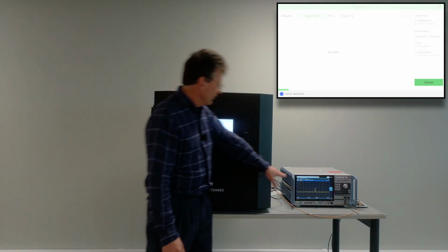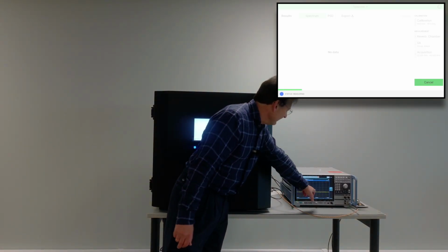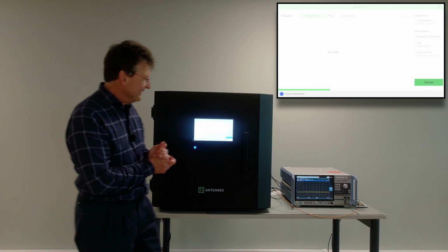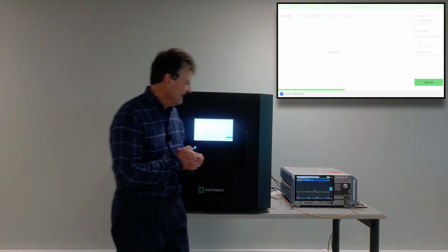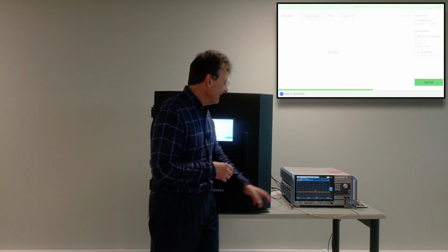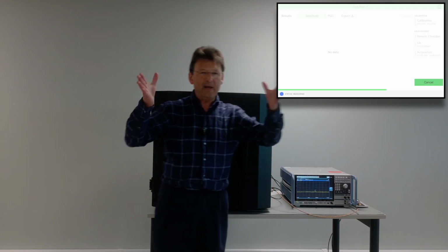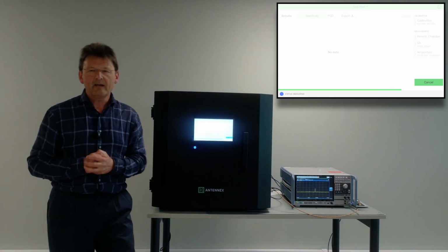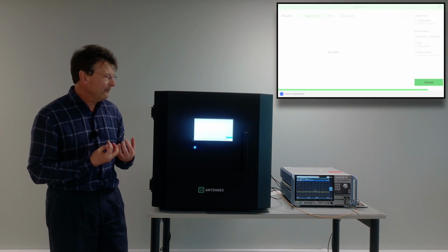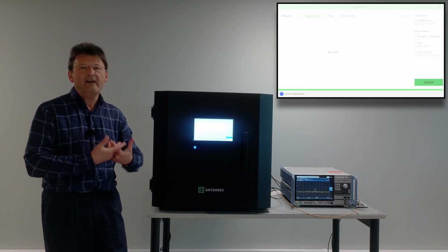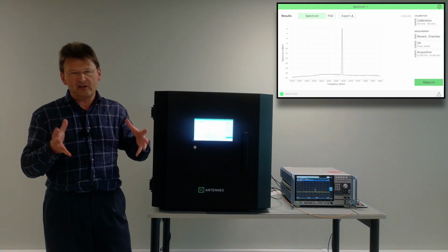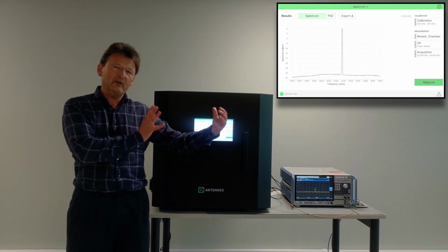And on the screen, you see the noise floor, and you see one spike moving up and down. So we are radiating at one frequency. And the nice thing of this approach is that very quickly, suppose you have LO leakage, suppose you have spurious signals, they also will show up within the span for which you were collecting the measurements. So it allows you to very quickly get insight into the behavior or the abnormalities of the device within one power measurement, basically. And just imagine that you need to do that in an anechoic chamber.